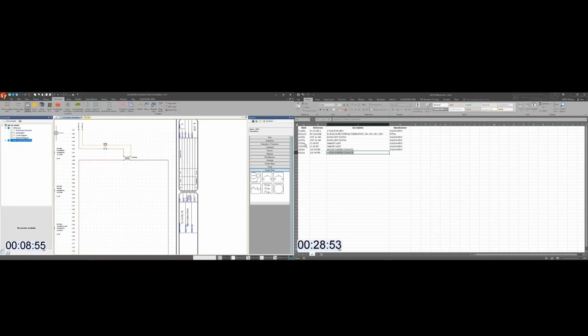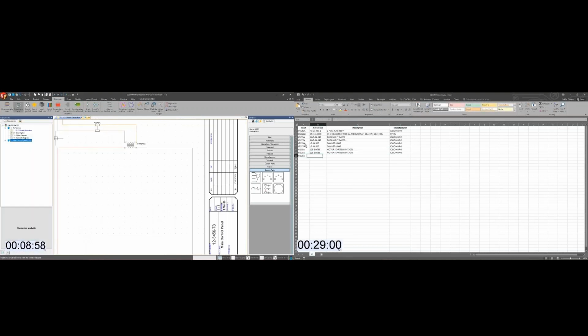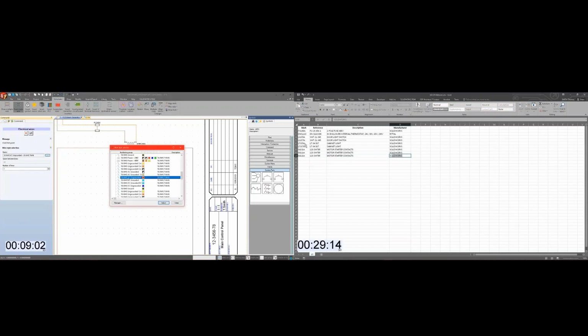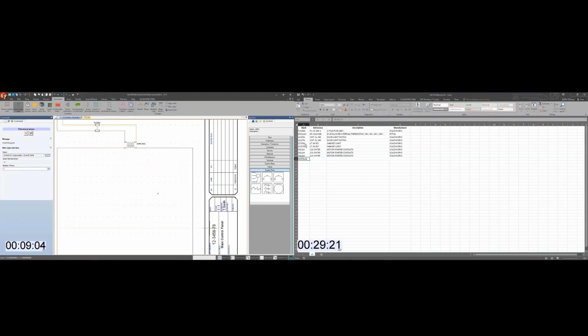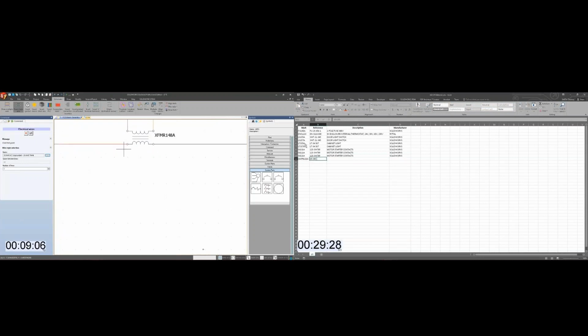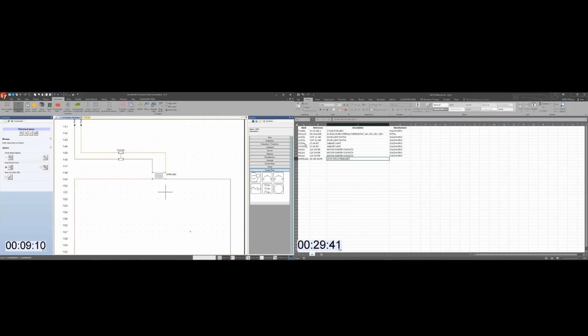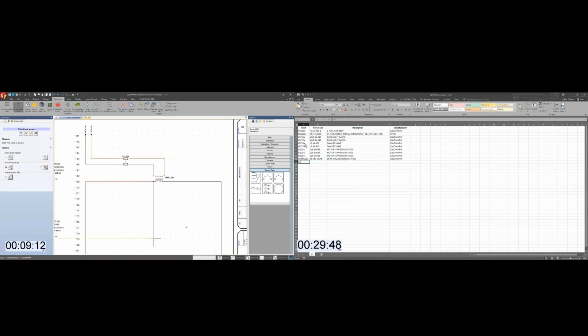Checking back in, we're going into 9 minutes in SOLIDWORKS Electrical, getting ready to build out that little circuit for the cabinet lights and door switches. Here I'm just putting in intelligence. It knows snap points. I'm using ortho to help me ensure that I'm drawing in the appropriate direction. So you have all the features you're used to: snap, object snap, ortho mode, grid, etc.